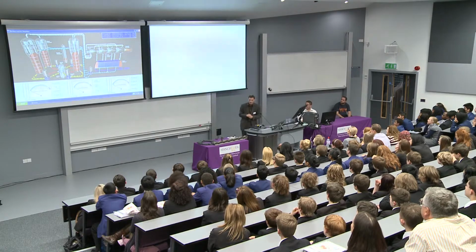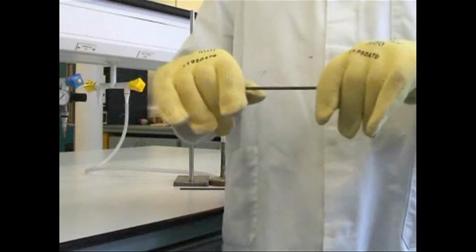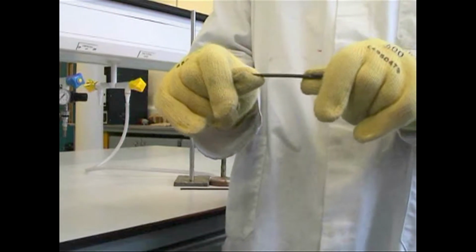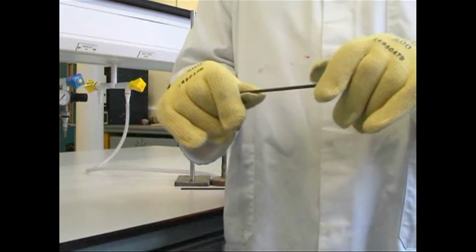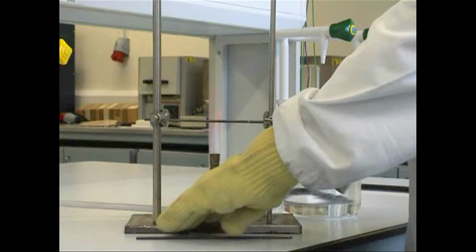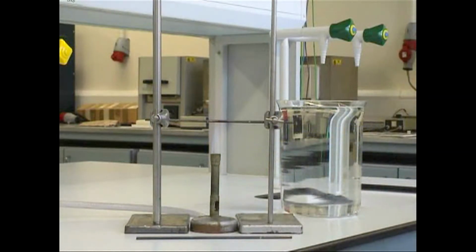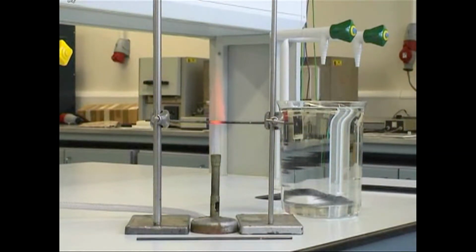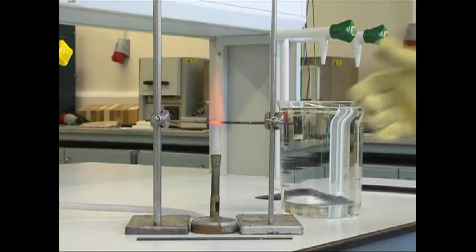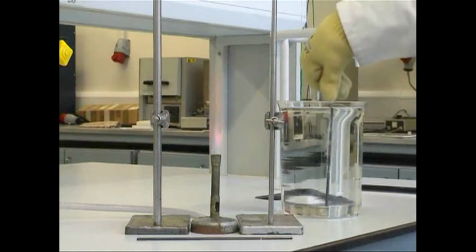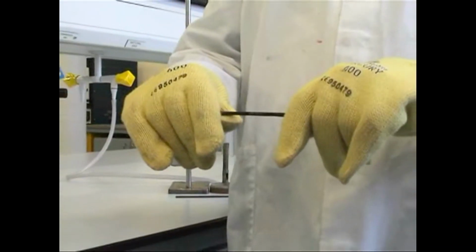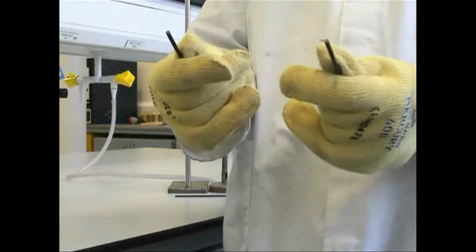And this is an experiment that we undertook at the university here. So here we've got a little steel rod which is quite strong, and you can see the microstructure down there. The microstructure makes it very strong, makes it very hard to deform the material. But if we heat that material up, we actually change the microstructure within that. So now it's heated to red hot. If we then put that into very cold water, we quench it, and that changes the microstructure, and it changes the properties. So all of a sudden, that steel that was very strong becomes brittle, and you can actually snap it like a twig. So the microstructure is very, very important.